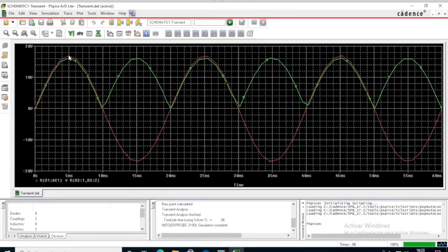Here we can always see a little difference, and that's because of the diodes. Each one is about 0.7 volts of difference, so the signal goes through 2 of them, and that's why the voltage drops a little, but not significantly.